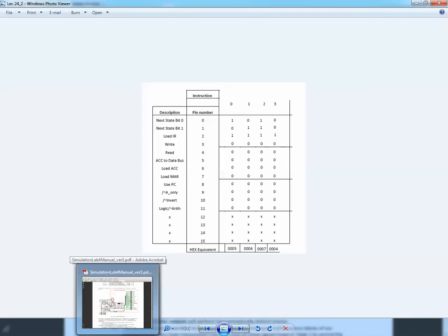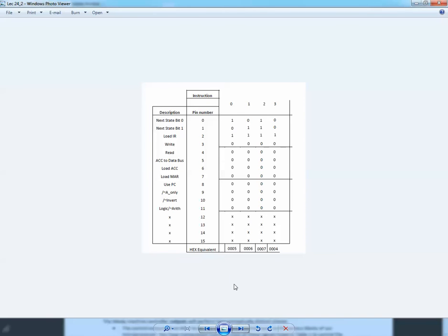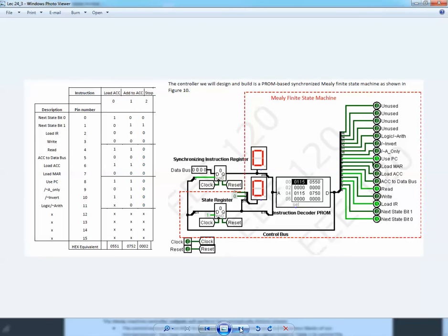So let's assume right now we want to add the 3 to 5 and then have the value of 8. So as we expect, we have only 3 cycles. 1 cycle, cycle number 2, and cycle number 3, which corresponds to the stop. So the first cycle corresponds to the load ACC. We load the value 3 and then add the value 5 and then the stop signal.